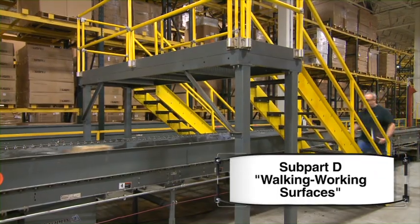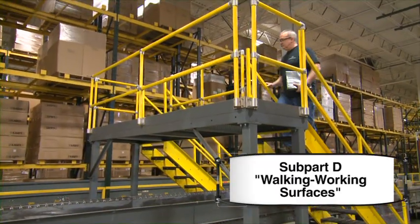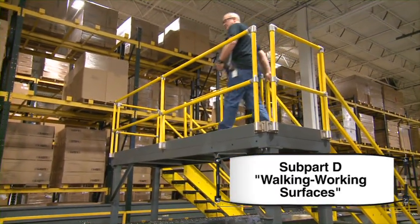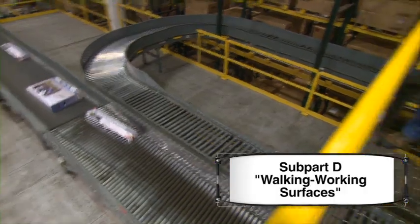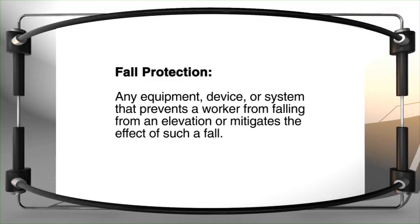Because of this, OSHA requires the use of fall protection when working 4 feet or more above a lower level in all general industry workplaces under Subpart D, Walking Working Surfaces. OSHA defines fall protection as any equipment, device, or system that prevents a worker from falling from an elevation or mitigates the effect of such a fall.